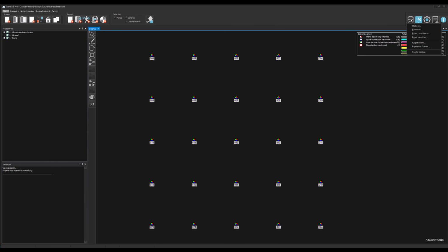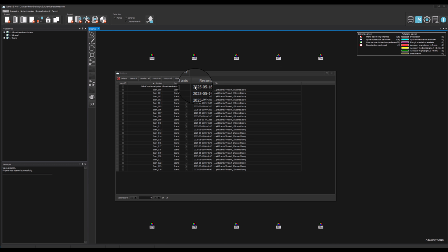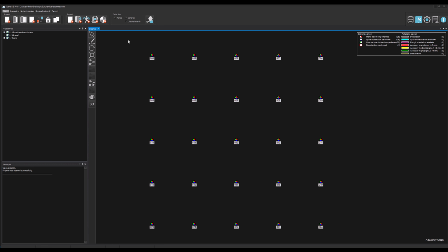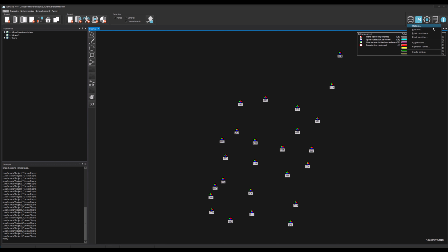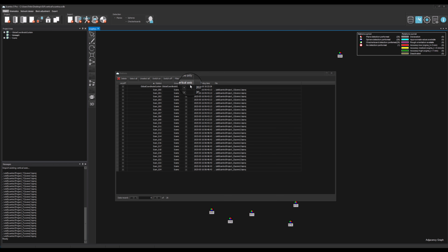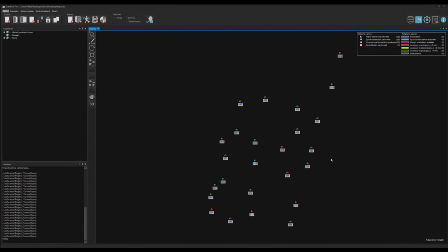Given the case that existing registrations or vertical axes have not been imported, for instance, due to mistakenly false settings, this can be achieved in retrospect by using the entry Existing Registrations and Vertical Axes under Import Data. After its selection, a dialog appears in which a user can choose to import either existing registrations, vertical axes, or both. This information can be retrieved from single scans or from supported project files. Should scans be selected in the graphics windows, this function will only be executed for these.